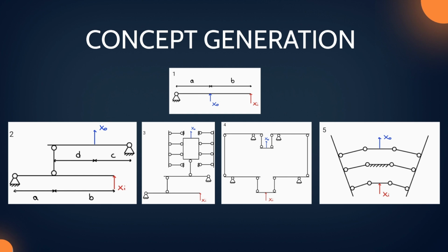The fourth option is centered around making the displacement as straight as possible by introducing symmetry over the axis of motion. Its parts are still derived from the double lever system. The fifth proposed concept is a symmetric system as well, but with a different layout of the hinges. This, compared to the others, is the most complex system from a predictability standpoint.